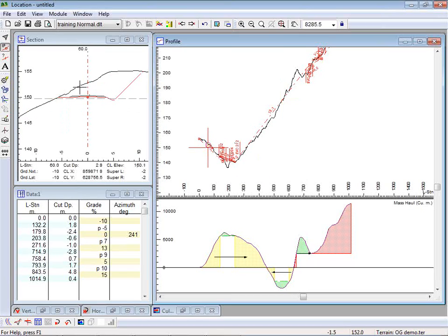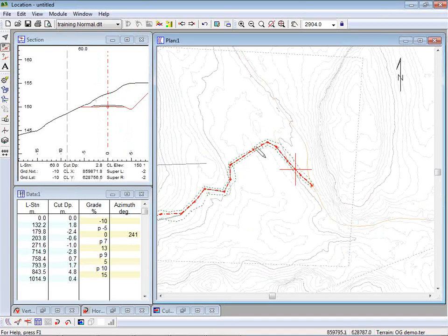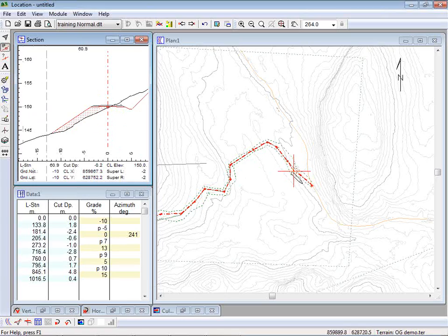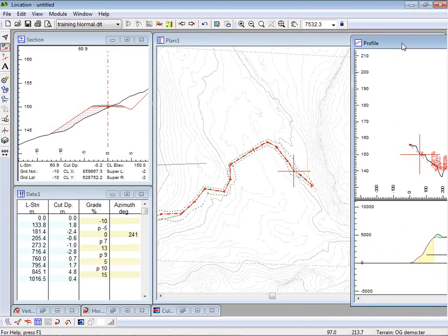So, yeah, let's look at that area. This is lots of cut, but it doesn't look like I have much choice here. I could move those points over a little bit, but not too far, because it's pretty steep. Yeah, I don't know. I'll probably get away with a little fill there. Whenever I move the horizontal alignment, I'm going to have to check vertical. So big monitor, watch them at the same time. Profile and plan can be visible at the same time.